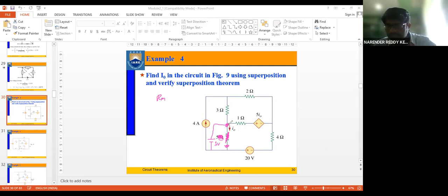So if I connect a circuit like this on a breadboard, and if I connect an ohm meter here, I can get the value of RTH, isn't it? That's what we are going to get here. It has 4.8 ohms, isn't it? So what is VTH now? Instead of using an ohm meter, if you use a voltmeter here, what value are you going to get across these two terminals? Then you call it VTH, isn't it?